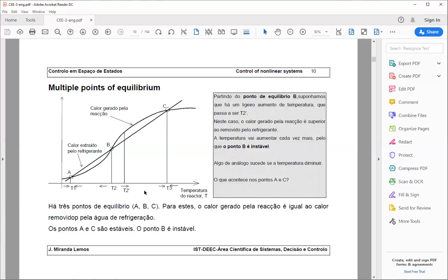So in a linear system, you can say the system is stable or unstable because you are mentioning only one possible isolated equilibrium point. But in nonlinear systems, you should never say it's a stable system or unstable system. You can only use these qualifiers for points, for equilibrium points.